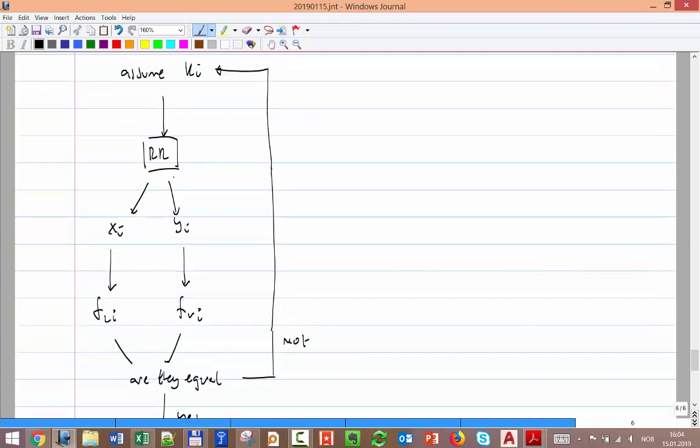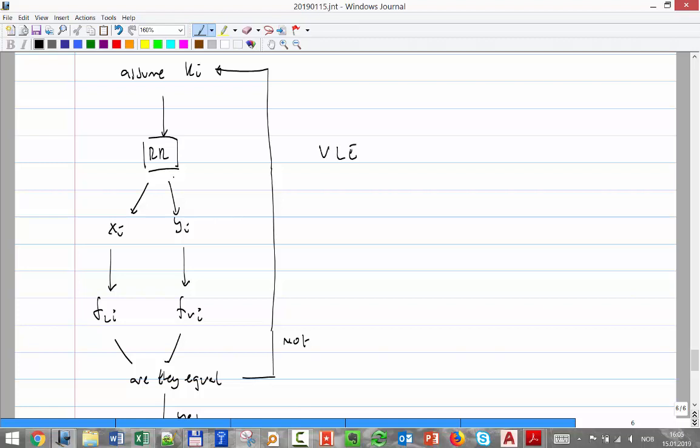So far we have said that for those K values that we calculate with the equation, these are correct, and I don't have to do anything else. But now with the equation of state, I have another option. I can calculate the energy of the component in the liquid and in the vapor, and then compare. If they are the same, yes, the assumption you made is correct. If not, I have to again assume another case. We are not evaluating that. It's just to give you a very brief overview of how the process simulator you're going to be using is doing that inside. And this is called vapor liquid equilibrium calculations.